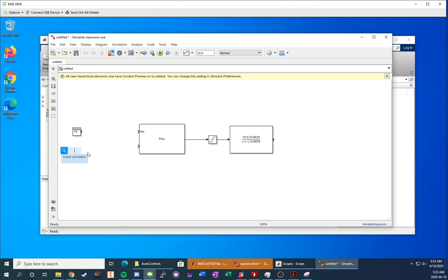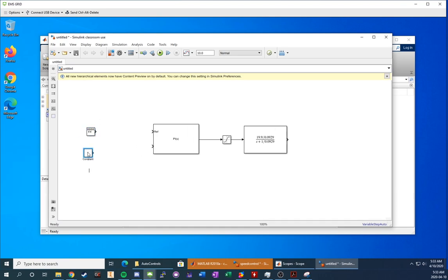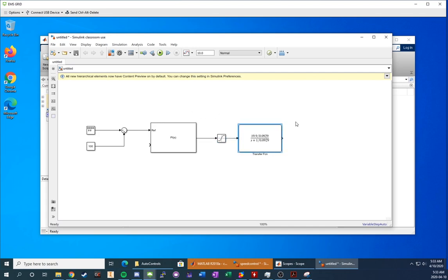We're also going to be using an offset, which we do by creating a constant. In our case, we're just going to set that to 100. It really depends on which section of the lab for each one of these particular blocks. We're going to need a sum block. In this case, the standard 2 structure will be fine. I'll show you how to change it when we go to the next one on the other side, but this is just going into the ref signal. Let me just make it look a little bit prettier.